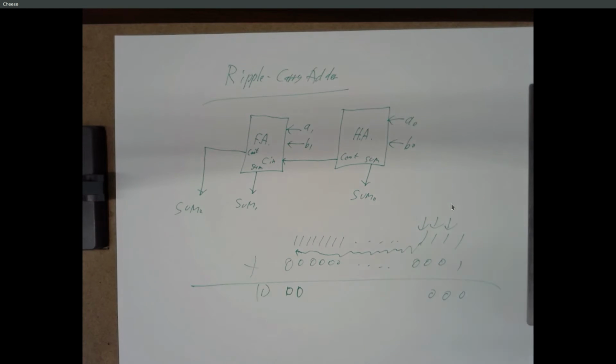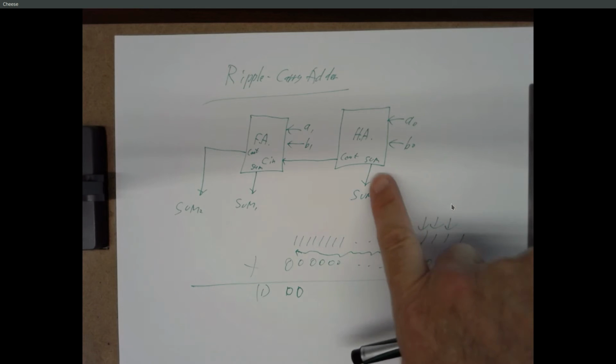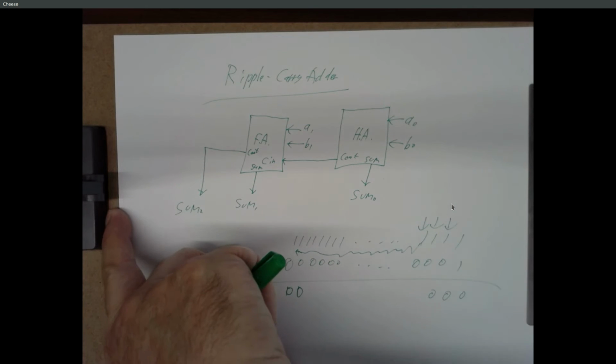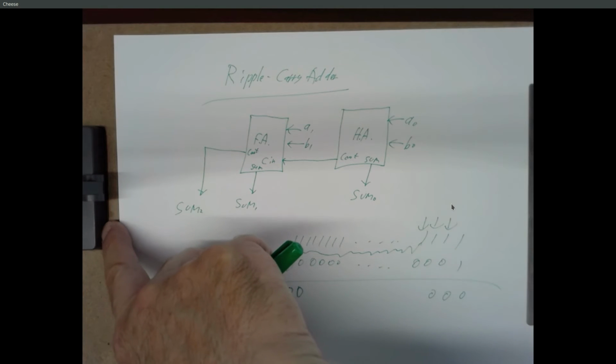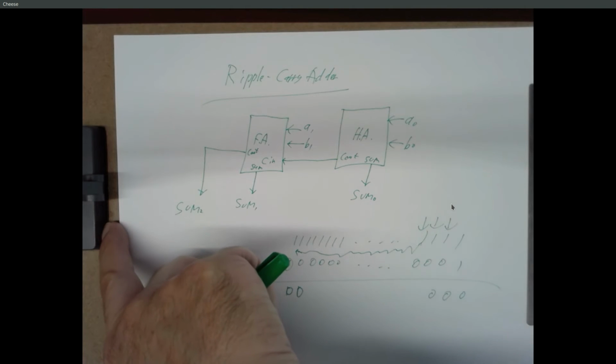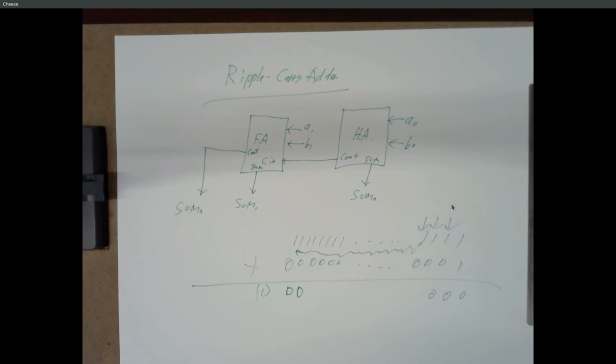So there's a whole branch of computer architecture just dedicated to designing circuits that do fast arithmetic. And there's lots of clever stuff that's been done, for example, to do very efficient addition of wide numbers. And why do we care about adding numbers? Because when you multiply, you're basically doing a lot of additions. Because how do you multiply numbers? Multiply by the first digit, multiply by the second. You get a whole bunch of partial products, and then you have to add those together. And if you're multiplying 1,000-bit numbers, you'd get 1,000 partial products and add them.